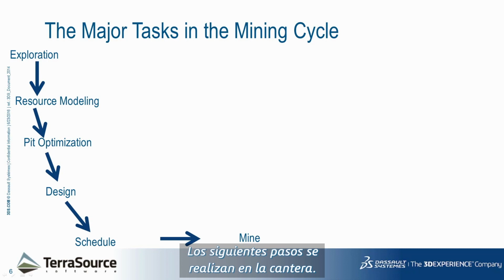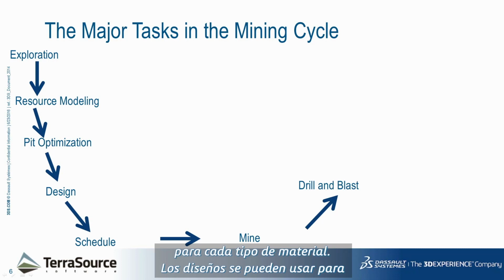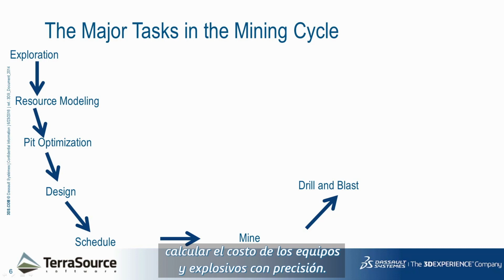The next steps are within the quarry. Drill and blast is where blast holes can be designed to the optimal pattern for each material type. You can use the designs to accurately estimate the cost of equipment and blasting supplies.